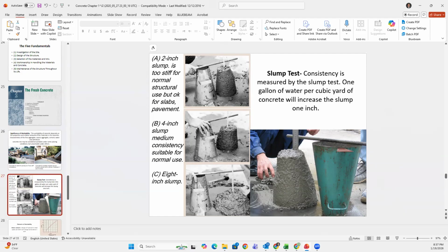Professor, just for clarification, you mean you have the concrete and it compacts or reduces in length by 4 inches, or pieces of it start falling off? No, it's the water. As soon as you dump it, your soup, your mix, starts losing water. If it has got too much water, it sloughs off completely, it goes down.